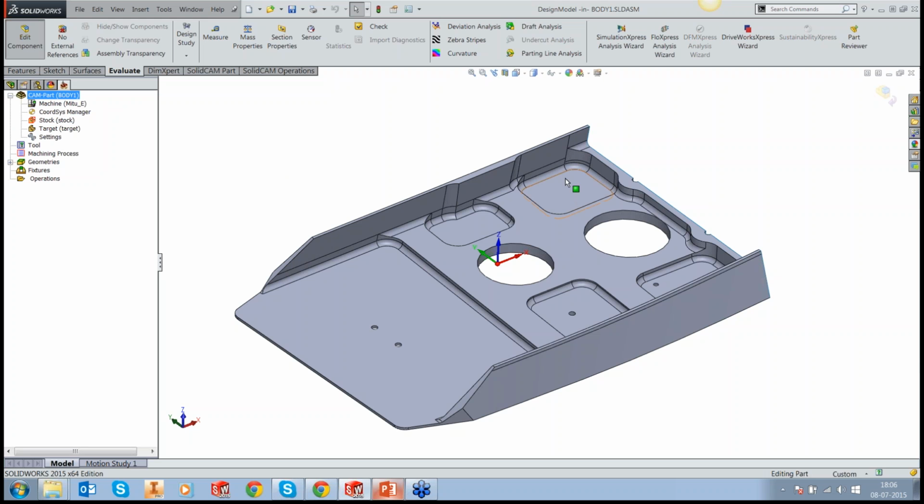So if you want to cut undercuts, now remember that you can't have undercuts of 45 degrees and expect it to be handled by HSS. Of course, it's possible, provided you use the dovetail cutters. It is still possible, but let's be more practical. If the undercut is such that could be handled by a slot mill or by a lollipop cutter, then trust that HSS is going to do the work for you.